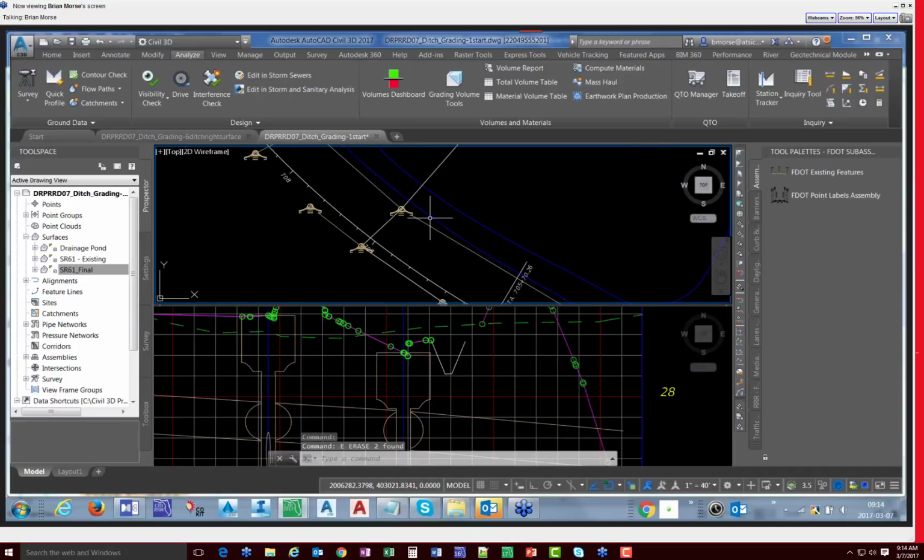So this is a 3D polyline. If you grip on it, it has elevations that match the surface. Now this is why I turned on my coordinate display, because I'm hovering over a grip, and that coordinate display shows 30.37 as the elevation. Okay, so down here, coordinate display.